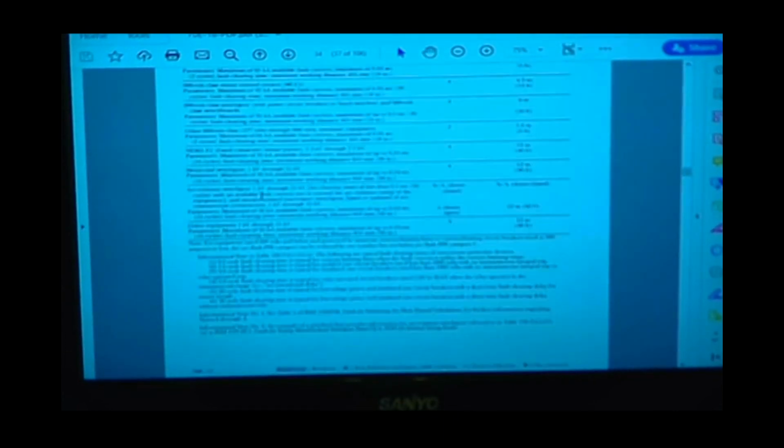So under these charts, there's a lot of people who don't have equipment labeled, so these charts are pretty well defaulted. Well, generally you got to have a pretty big facility to get over 25 kiloamps of fault current. Well, do you know if the breaker is going to clear in 2 cycles or not? All you got to do is look at it. If the breaker is discolored, it's probably not going to trip. If the breaker is broken, it's probably not going to trip. If the fuse is discolored, it's probably not going to trip. So it's a visual inspection to identify. But once you identify the type of PPE you need, now we can take the PPE from a chart.